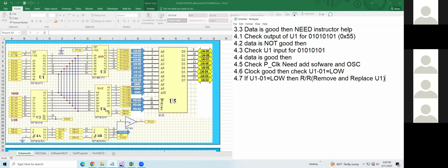The thing is, you build a circuit. Check the wires. I connect the meter to U1 pin 2. Then I remove the wire, lift it up.